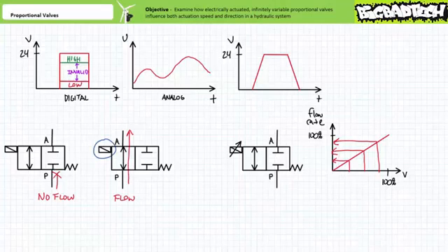Additionally, proportional valves sometimes include sophisticated feedback mechanisms that allow them to not only receive an input signal, but also send an output signal that can be monitored by a control system to perform incredibly stable, precise, accurate, and repeatable movements of an actuator despite a changing external environment. I'm not sure if you can tell or not, but I'm getting kind of excited here, because proportional valves blow wide open the doors of many advanced topics, including open and closed loop control, PID control, and more.